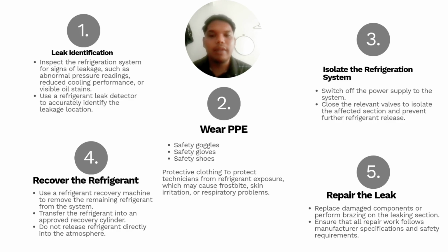The next step is refrigerant recovery. A recovery machine is used to remove the remaining refrigerant from the system and transfer it into an approved recovery cylinder. Refrigerant should never be released directly into the atmosphere because it can harm the environment.